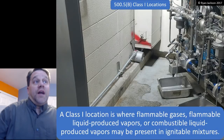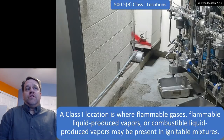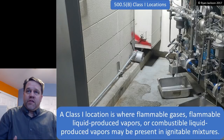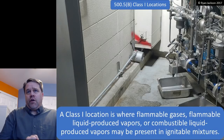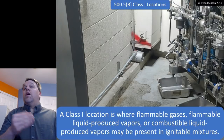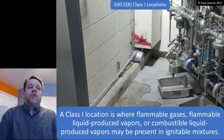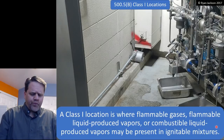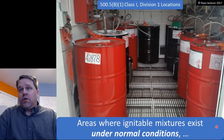So getting back to Class 1 locations, a Class 1 location, once again, is an area where flammable gases, flammable liquid-produced vapors, or combustible liquid-produced vapors might be present in ignitable mixtures. And now we know what those things are. So flammable liquids are what? Less than 100 degree F flashpoint, and combustible liquids are greater than 100 degrees Fahrenheit. So the vapors produced by them, if those are present in ignitable mixtures, then we have ourselves a Class 1 location. We break down Class 1 locations into two subcategories: a Class 1 Division 1 location and a Class 1 Division 2 location.